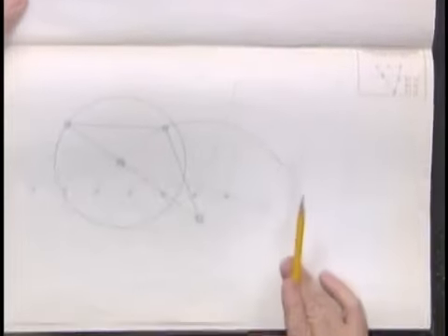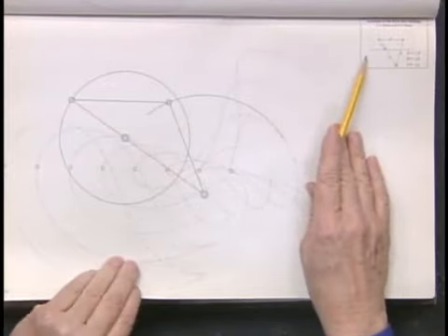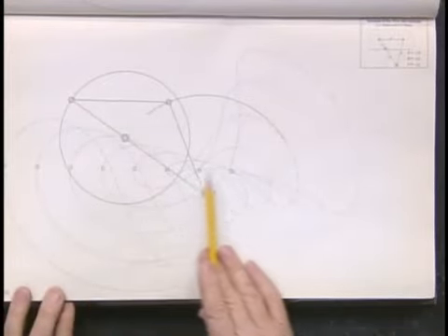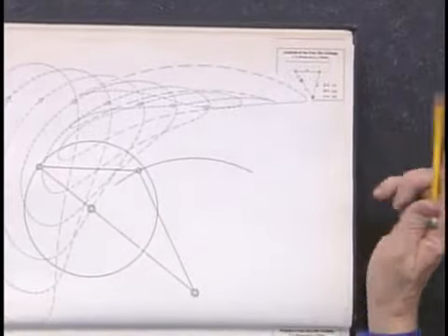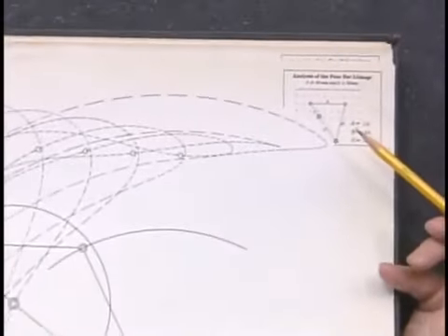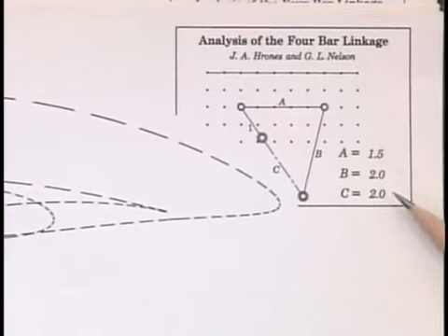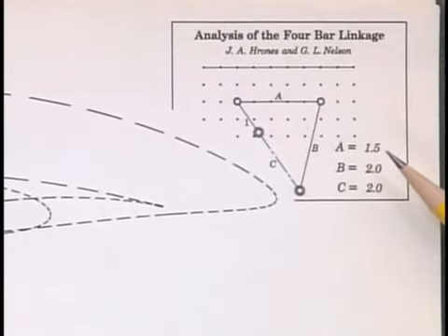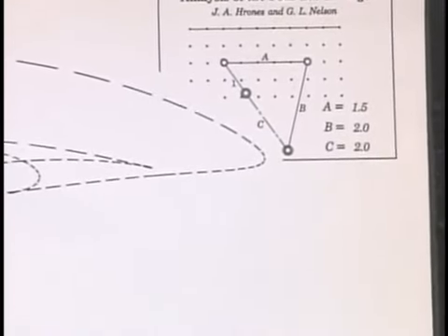And finally at page 5, we are at the bottom row of the coupler. And our curves are now down here with respect to the linkage geometry. I'll go one more page to show you that, and perhaps now we can zoom in on this little corner again and show that now on this 6th page, we're back up to the top row of the matrix starting over again, but now the link ratios have changed to 1.5, 2, 2. They were 1.5, 1.5, 1.5 before. So a new family of links.